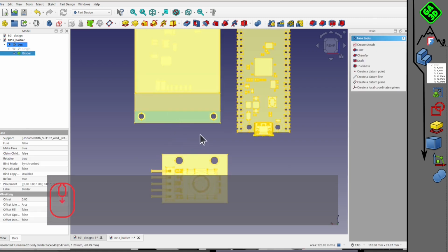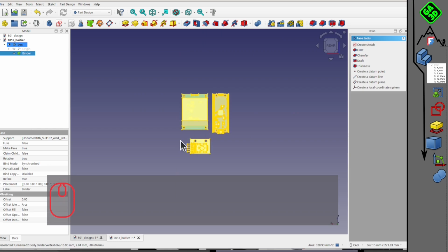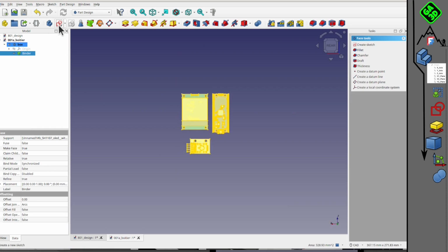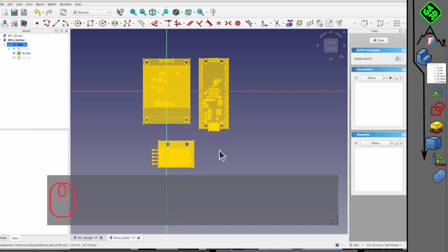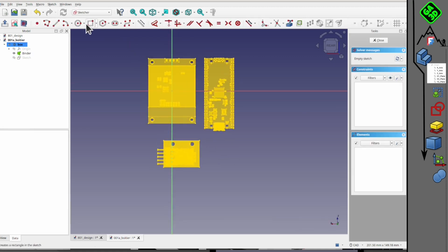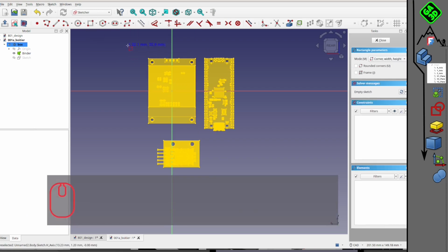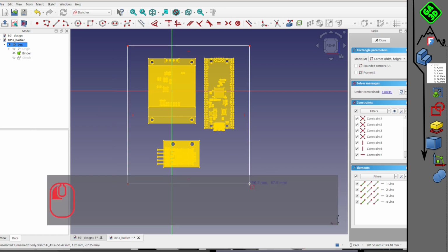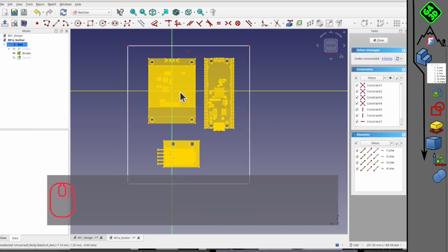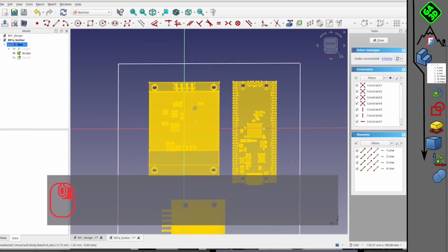We're going to create external elements in our sketch in wired mode, and we're going to put a rectangle around our screen, which will actually prevent the creation of the volume within the sketch.